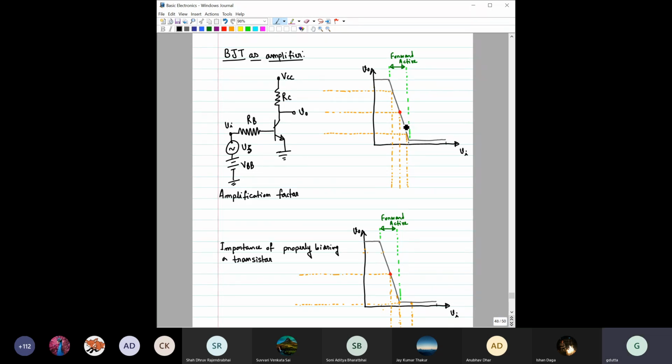seen the output characteristics would look like something like this. So this is around 0.7 volt, this is around 1.9 volt for the particular case which we have done in one of today's examples. But those values are also dependent on the other parameters of the circuit. So this value of 0.7 is fixed, but this other value depends on the circuit parameters, so you have to find it from the equation that we have derived today.